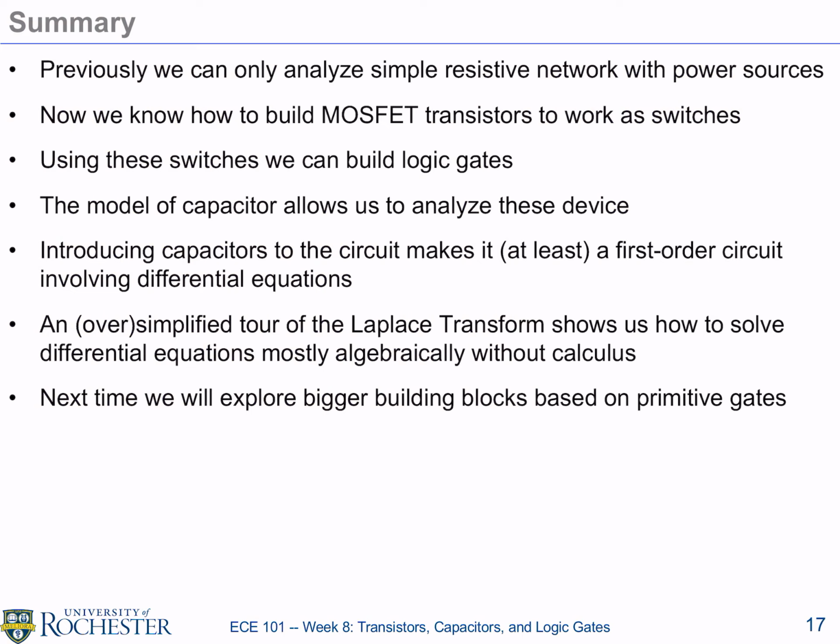So for an inverter, for instance, if the input is 1, the output is going to be 0. But if I really look at the voltage of input, I'm going to see as the input goes from low to high, the output is going to suffer some delay before it goes from high to low. So there is a finite delay. We draw these things with very square edges. In reality, they're all curved. But again, when we focus only on the steady state, we will say, oh, the input of this gives the output of that. And that's what we'll discuss next week.